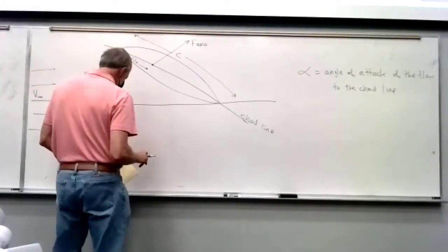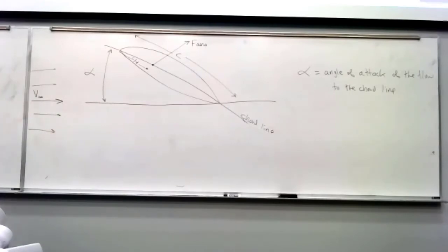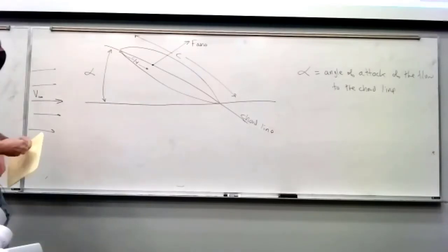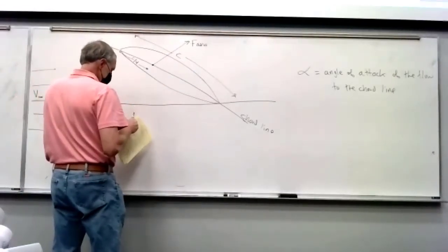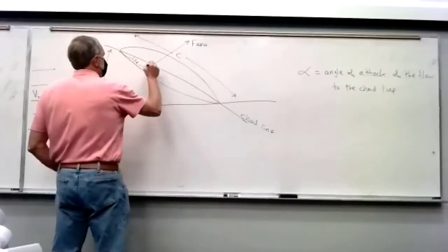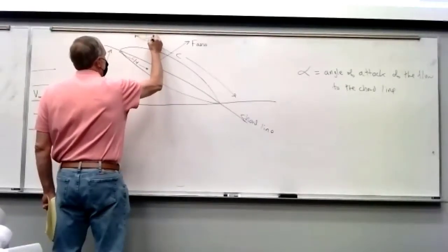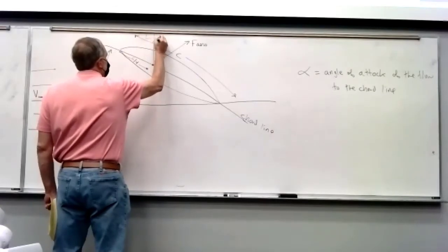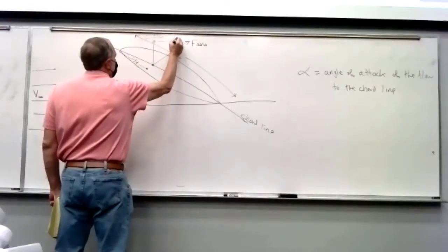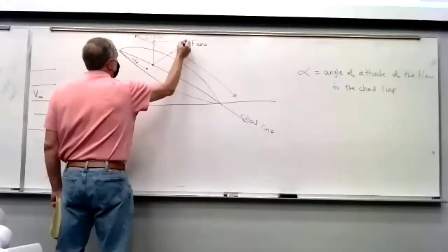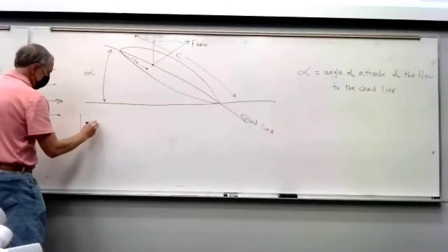All right, now this is important. These next directions you got to memorize because it's the definition. I'm going to break that force vector out into our component perpendicular to the V infinity. And I'll call that lift. This is perpendicular to the flow. And then the other component is drag and it's parallel to the V infinity. And that is by definition.